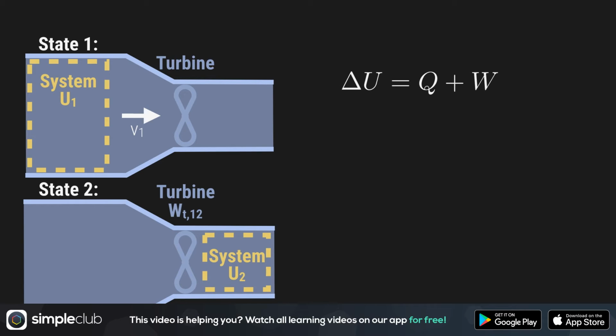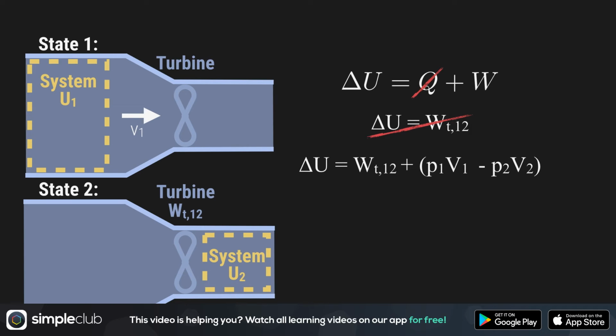The Q we can just cross out, since the system is adiabatic after all, and heat Q has to be 0 anyway. And work in this case is just the technical work from the turbine. Yeah, no. In addition to the technical work, we also have to account for the volume displaced by our mass. This is easily expressed as the product of volume and pressure, like here. Now we can solve the equation for the technical work, writing delta U over here.